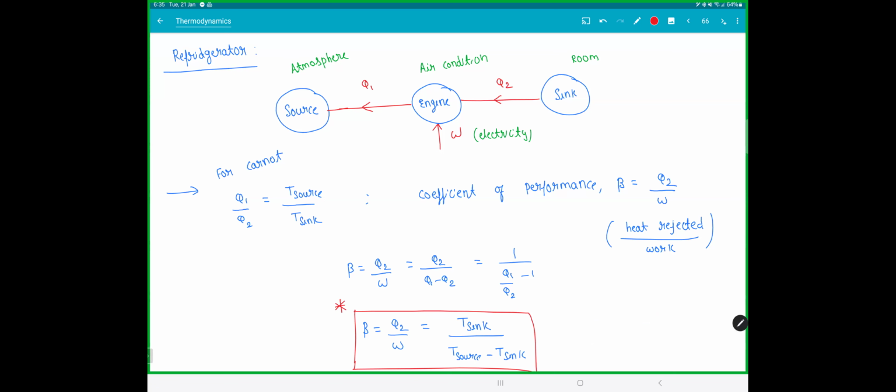So this is a reason, when you're switching on your AC, right? Normally people say this thing: instead of putting your AC at 16 degrees, it is better to put it at 24 degrees and switch on your fan. This feels the same as 16 degrees, but it consumes much less power. That 8 degrees of difference in your AC takes up more than 20-30% more electricity. So normally when we come from outside, what we do is put it on 16, we put a blast of air. Even nighttime when you're sleeping, instead of putting it at 16, it is preferable you put it at 24 and put a fan on.